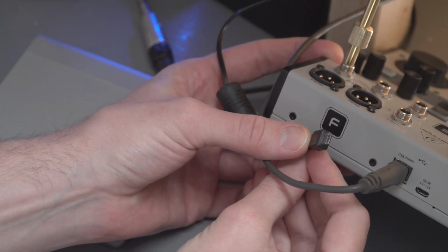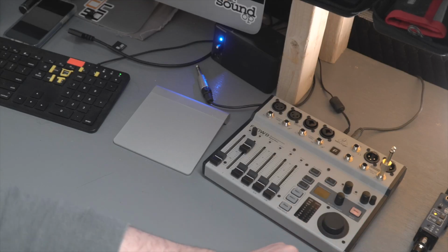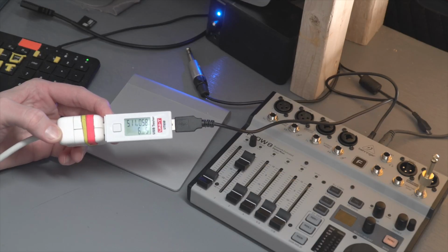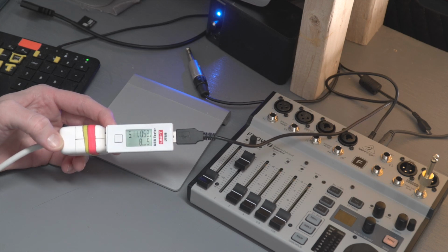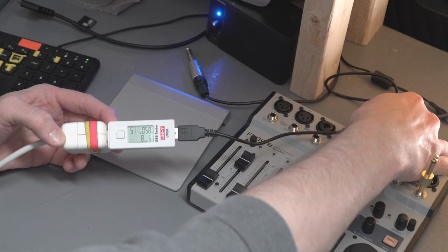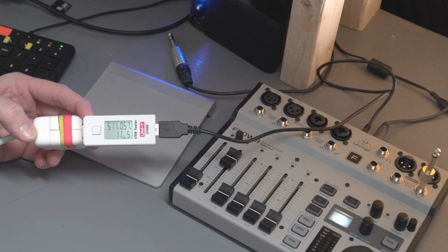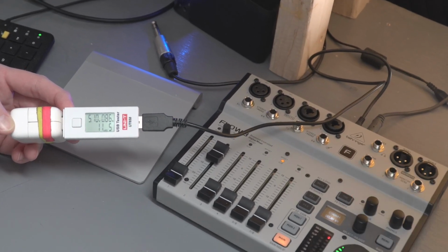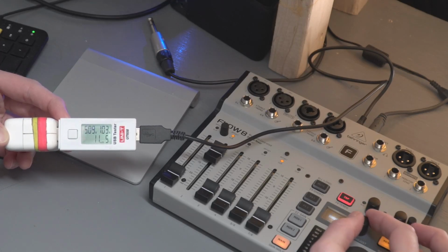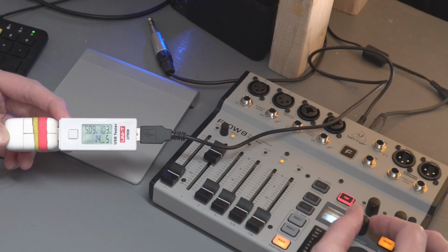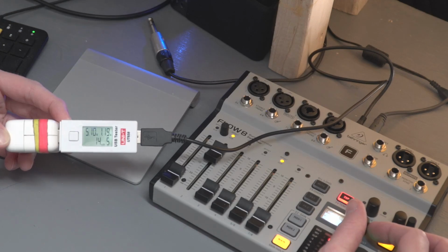Another common power question is, can you turn this mixer off, and how do you do that? It's done by holding down the menu button, though that's more of a standby. We can see using a little meter that the mixer still draws just over 500 milliamps when it's in that standby mode. So if you are powering it off a battery, you want to be aware of that. Overall power draw in use with this mixer is affected by how bright you set the backlight, if you're using phantom power, Bluetooth, etc. So your mileage will vary depending on what you're specifically doing with it. So be sure to test before you take it out in the field depending on battery power, but it is very light power draw and works really well in that kind of scenario.